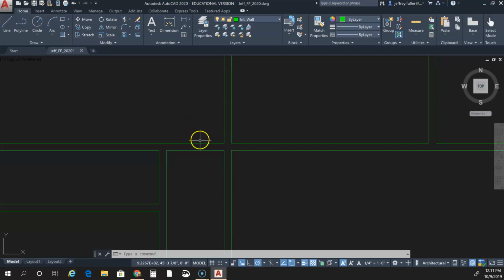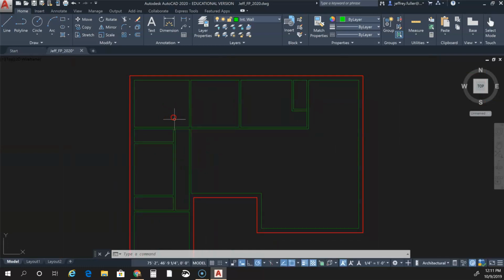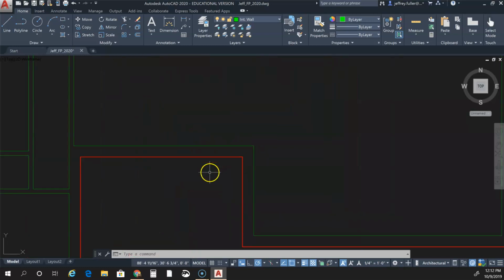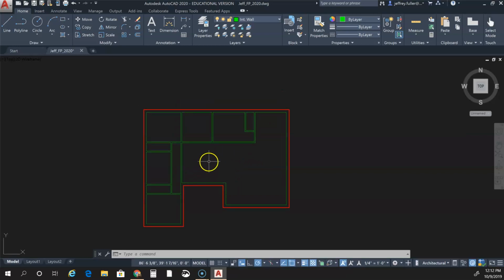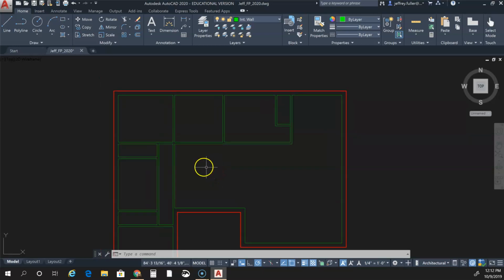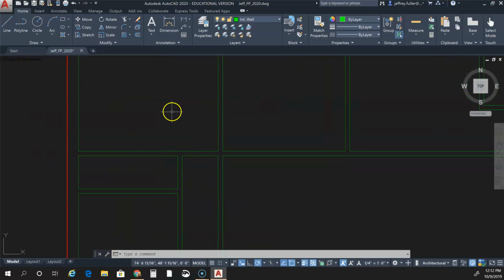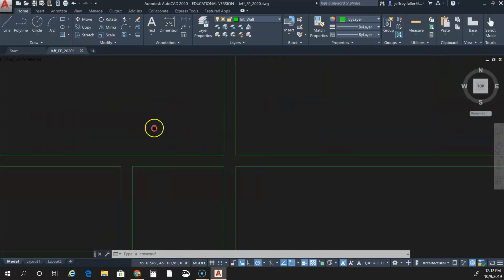So I'm going to use, in this case, a 30-inch door on all of my bedrooms, my bathroom, my closets. I'm going to go with a little bit narrower door. I might even go with a sliding door. And then of course my front door, I'm going to go ahead and go with the 36-inch, and that is recommended that you do that on the front door at least. And then things like back doors can be a little bit smaller, about 32 inches to 34 inches, something like that.